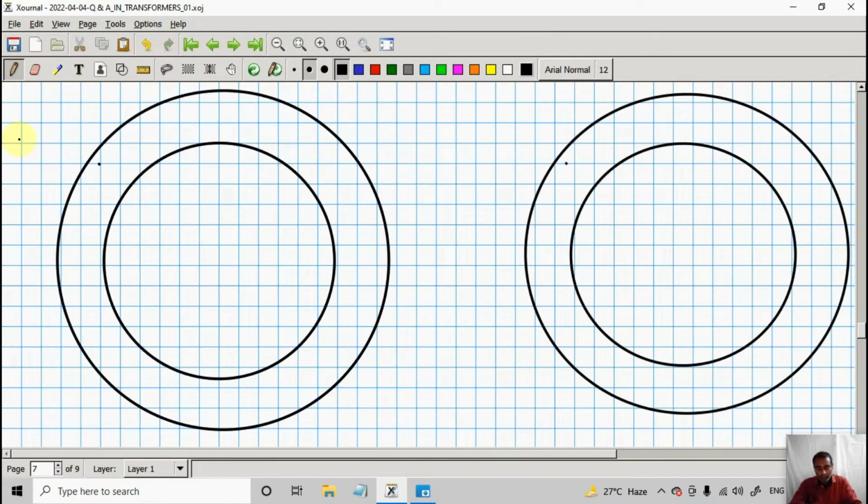We had started drawing the high voltage side by drawing three vertices as if they are the vertices of an equilateral triangle, and the three vertices will be named A2, B2, C2, starting from the top A2, then moving in clockwise direction, B2 and then C2. We have drawn the windings like this because the high voltage side was delta connected.